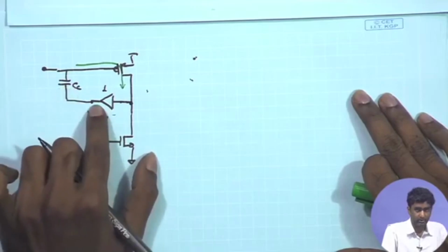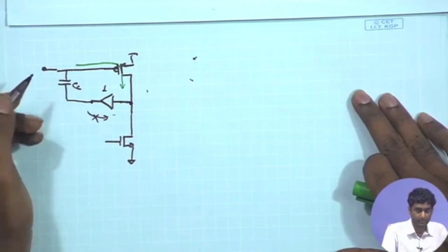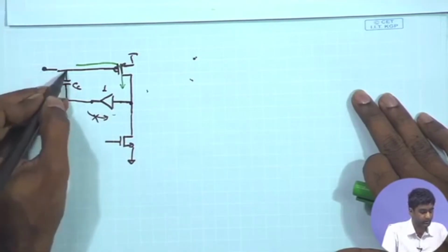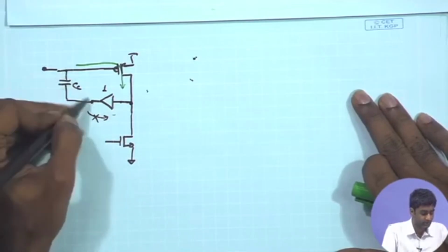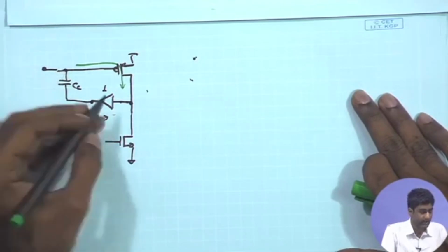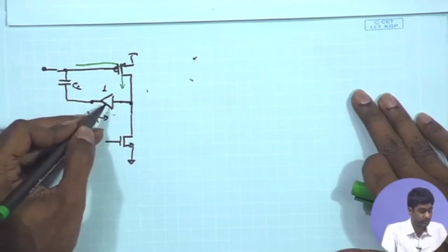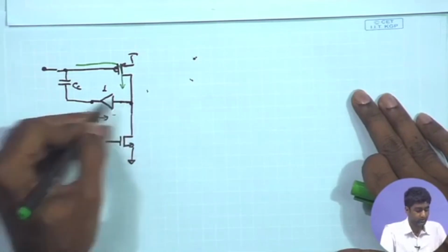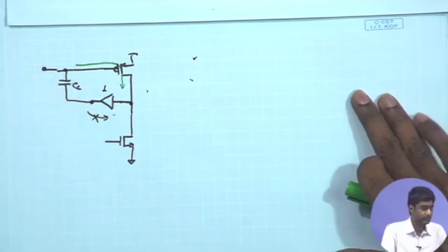Now, does it still have the Miller effect coming into the picture? Yes, because the gain is remaining the same. All you need for the Miller effect and the Miller compensation is that the gain between the signal or voltage level at the other end of the capacitor with respect to the first end should be sufficiently high, and that is not changing much because of this unity gain amplifier, because the gain from the output to this point is 1, therefore, the Miller effect remains intact.